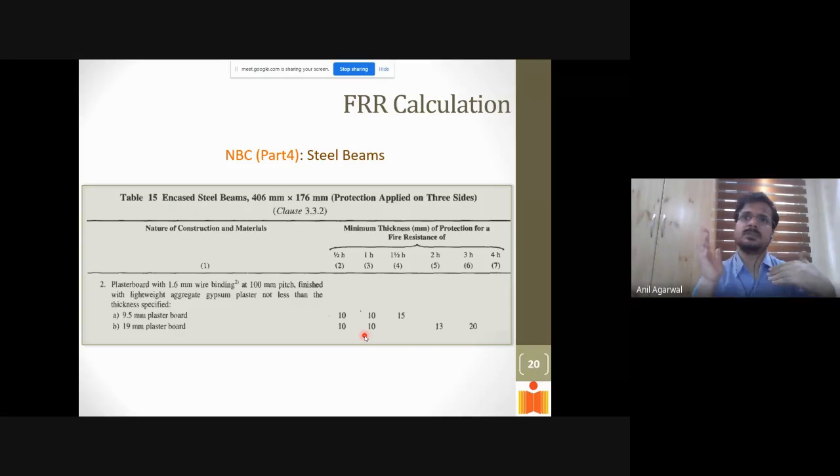We simply go by whether it's a beam. If it's part of a 10-story building, you need 4 hours of resistance for columns and 3 hours of resistance for a beam. So for a beam, you simply slap on 19 mm plaster with 20 mm plaster board with 20 mm plaster. That's all. As simple as that. But that approach is flawed. There are a lot of issues with this kind of approach. There are issues of what kind of standard fire was used to develop these curves, but those are more nuanced. Even at a fundamental level, there are many issues.